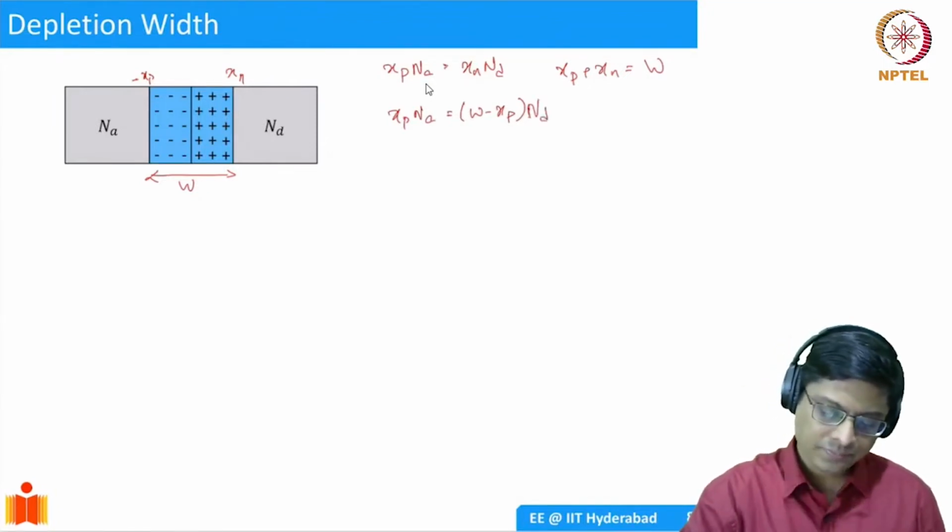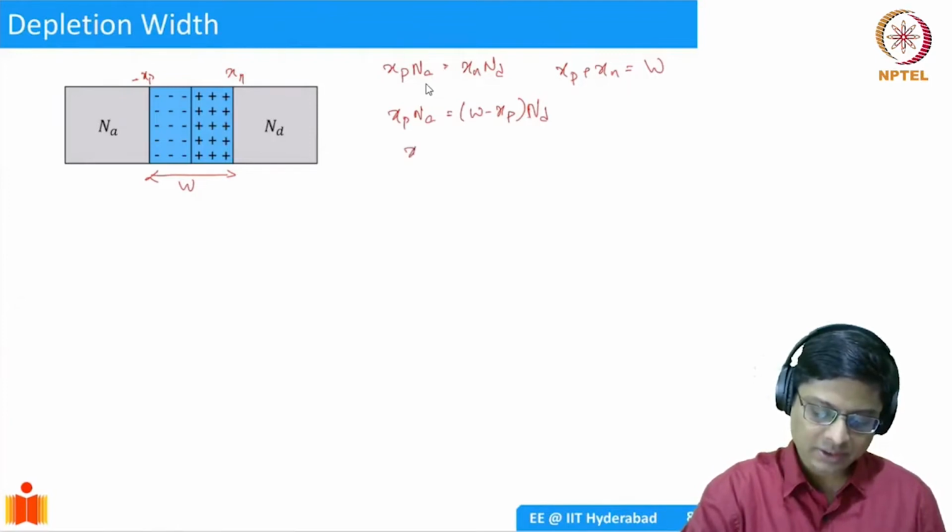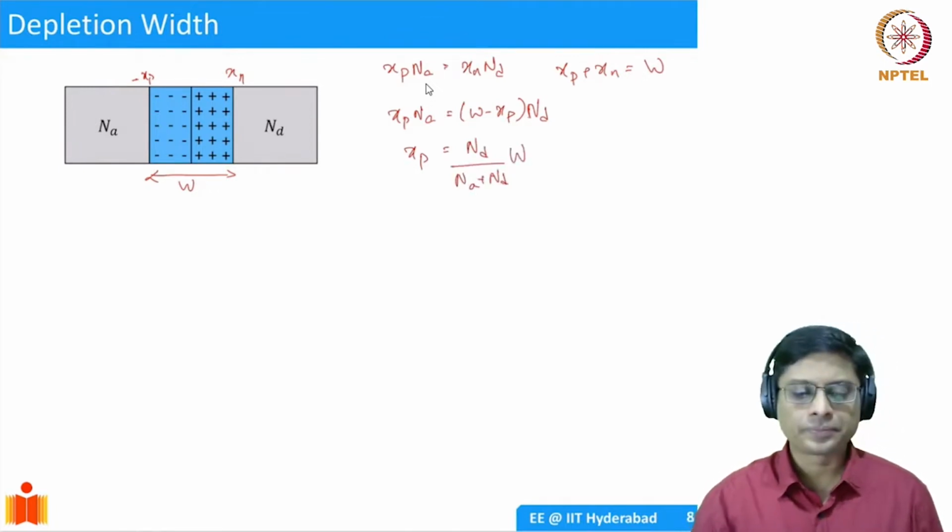So I'll take it to the other side, and then I'll take the Na to the other side. So xp is going to be Nd by Na plus Nd times W.